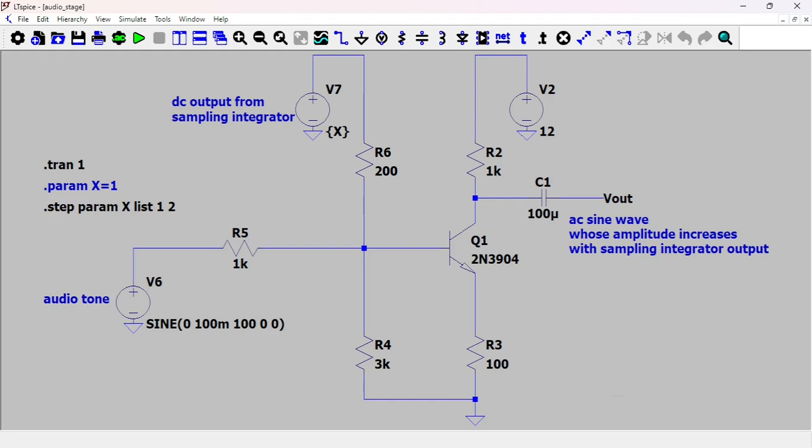So using loudness to indicate that there is a metal under your coil, that's one way to do it. The other way would be to use what's called a voltage controlled oscillator, a VCO. So when we talk about VCO, we mean that when you are away from the target, you have a background sound that is usually pretty low in frequency.